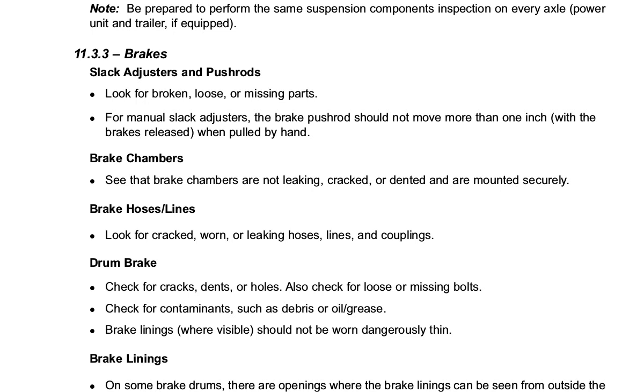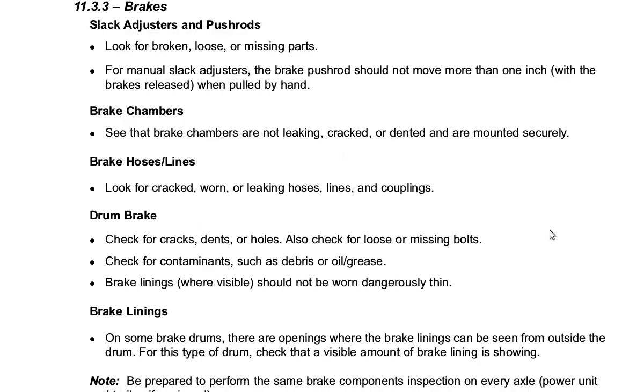Brakes, slack adjusters, and push rods. Look for broken, loose, or missing parts. For manual slack adjusters, the brake push rod should not move more than 1 inch with the brakes released when pulled by hand. Probably need to remember to chock the wheels.